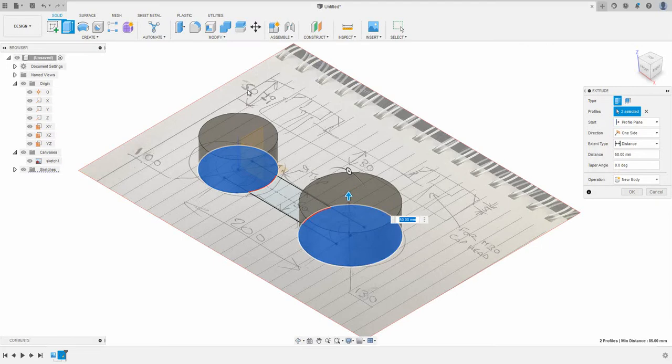I want this to be extruded to, now we've got to be careful here, because the dimension I've got is 50 plus 0 minus 1. Now if we were machining this, we need to make sure that we are at least giving the machinist a chance. So we really want to give him a mid-tolerance. So the best thing we can do with this model is to actually put this at a dimension of 49.5mm,